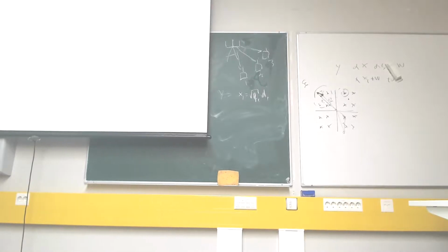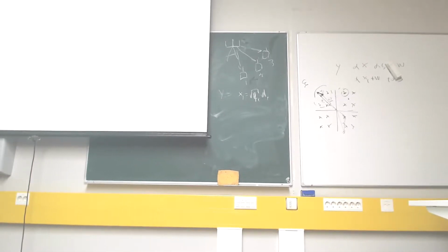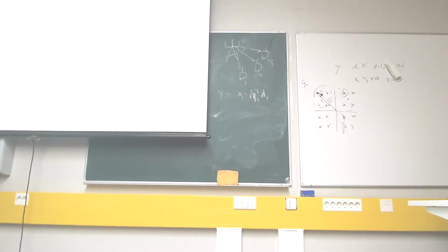All right, so the received signal in the dual uplink consists of the desired signal at the output of the received beamformer, u_k Hermitian h_k x_k. x_k is now defined over there, right?